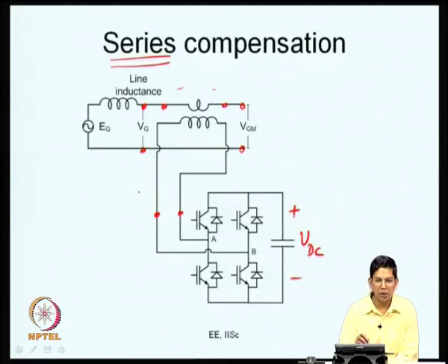So, the voltage that is being injected in series will add up to the mains voltage and make the resultant voltage a waveform of acceptable quality. So, the voltage amplitudes will be okay. If there is any unbalance, that unbalance would be set right, and if there are any distortions, the distortions could also be reasonably set right. So, you can produce 3 phase voltage waveforms of acceptable quality by following a similar approach.